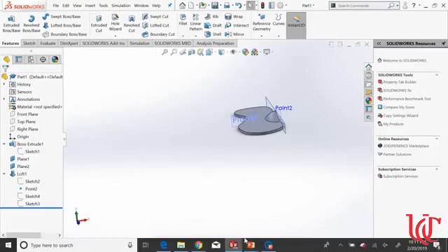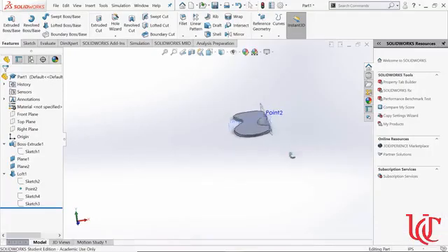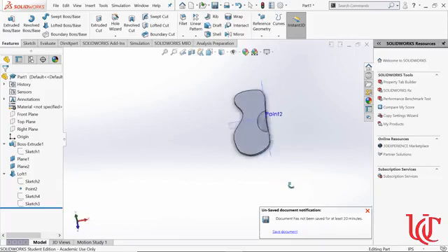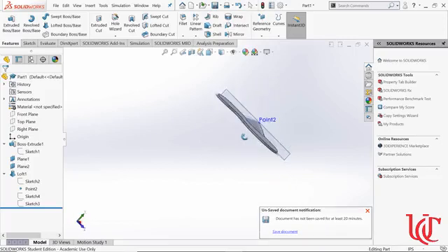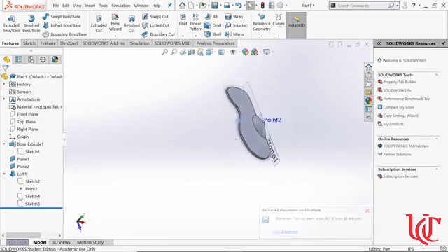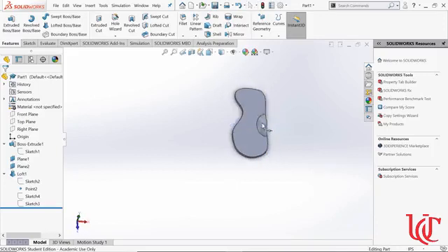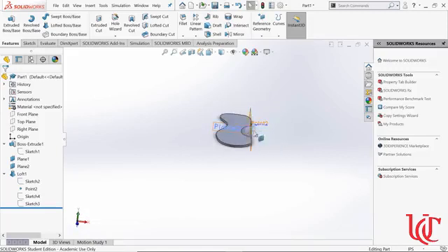So, in SolidWorks, I'm going to show you how to make this part. This is a very rough version of a kind of orthotic. I expect yours will look very different and probably much better than that. But I just made some solid as a base, which I extruded up. There was this weird shape. I actually made that shape from my spline command. And then I had something that was kind of like my arch support here that I would need as a separate 3D feature. And I'm using that with a loft with guided loft curves. So it's kind of a weird curvy shape, and I'll show you how to do both of those now.